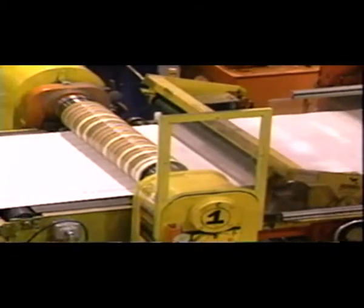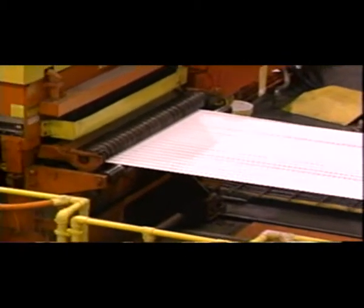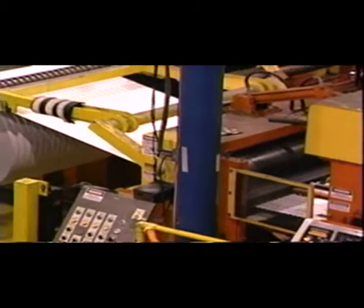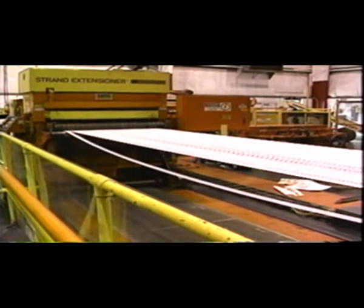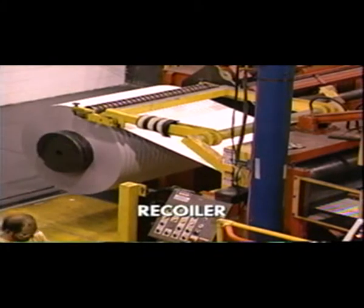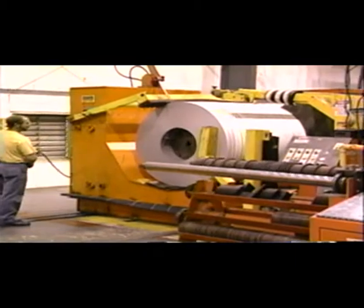Since most master coils are crowned or bowed in the center, the processed center coils wind to a larger outer diameter than the end coils. The result is that the center coils pull tight as the end coils hang down loose. A tensioning device is generally employed between the slitter and recoiler to adjust for this length differential problem. The recoiler takes up the processed coils on a mandrel, where they are removed onto auxiliary handling equipment.